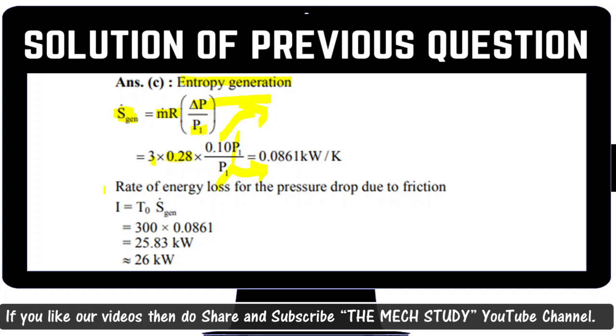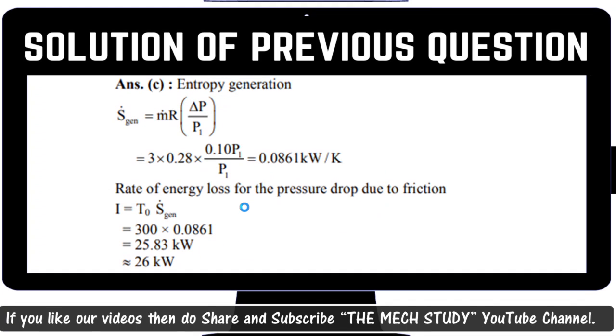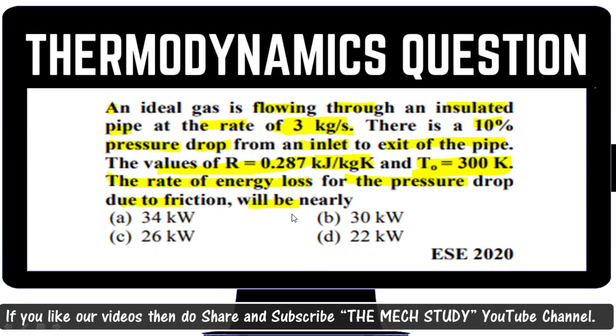So the rate of energy loss for the pressure drop due to the friction is I, irreversibility, equal to T into delta S. Delta S is the entropy generation of that particular universe. So I equals T0 delta S, and T0 they have already given as the ambient temperature 300, and the entropy generation is 0.0861, which you have calculated over here. If you put all these data over here, you will get 26 kilowatt as the final answer for the entropy generation due to the loss of pressure. That is, option C is the right answer for this question.